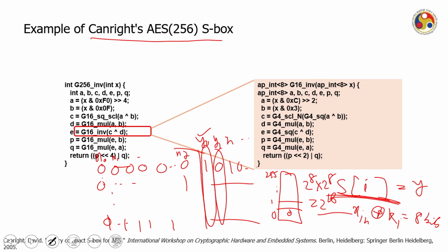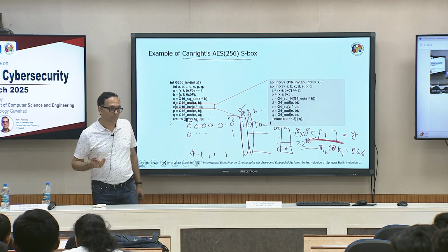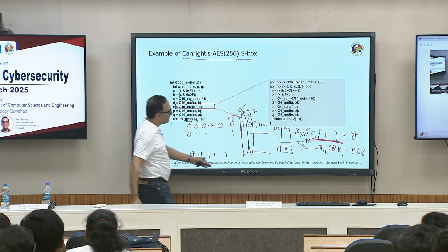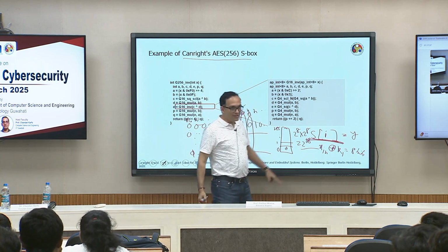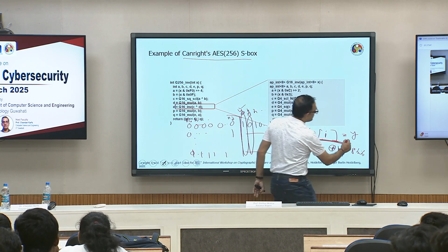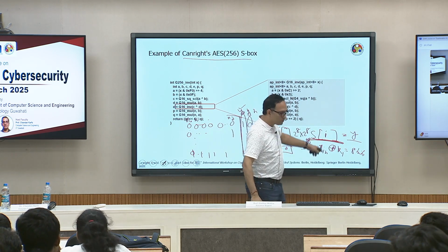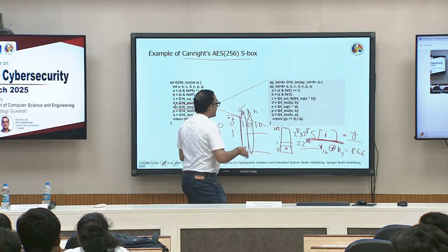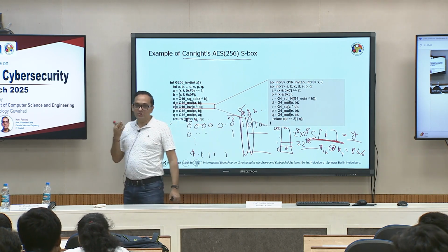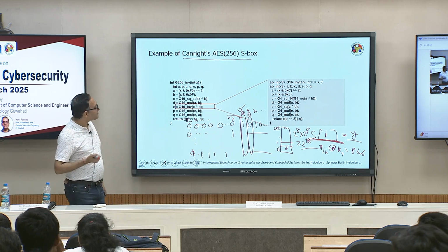Everyone understand this concept? I do not need to make this 2 to the power 16 memory. Instead, I know the values of 0 to 255 for both, I make this table and identify the relation between y0 and the inputs. This is what you do in your Karnaugh map minimization.